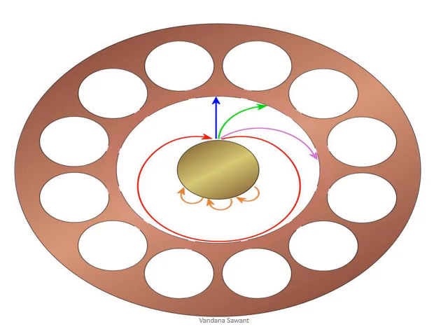That is, the electron should move through 180 degrees from one cavity to another cavity. The magnetic field at which this takes place is called the critical magnetic field. So whenever the magnetic field is equal to the critical magnetic field, the electron will take the violet color path. This violet color path is indicated in the figure.